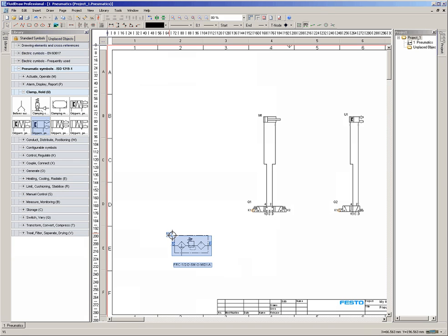To draw a connection line, click with left mouse button at a symbol's connector. Move mouse a little with pushed button, then release button. To set a support point, simply click with left mouse button. Finish drawing of connection line by click at another connector.